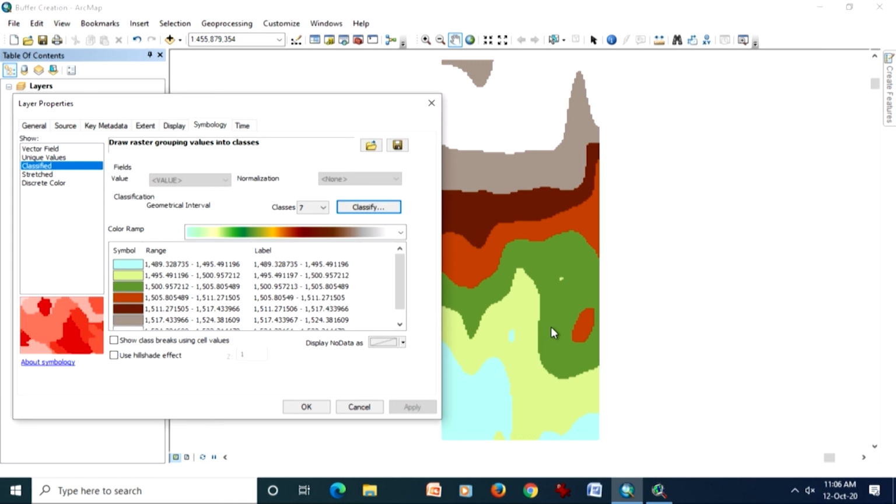See, the theory generally will tell you what things are available and how things are done. But when we come to implementation or application or using some software, then various options are available to us. Like when I was talking about buffers, you can create multiple buffers in ArcGIS also, maybe not in one go, but in multiple steps. Basically there are no instructions, nobody will tell you how many rings or buffers you should create, or what the distance among these buffers should be.